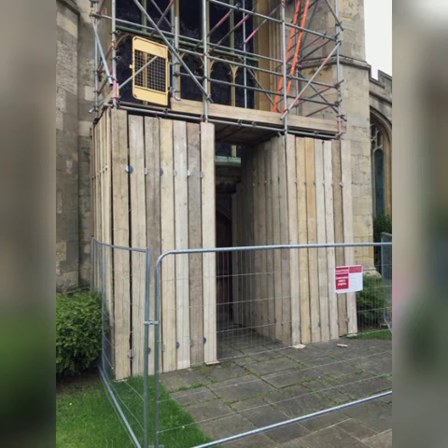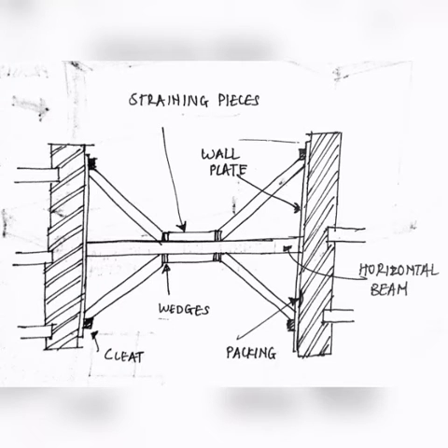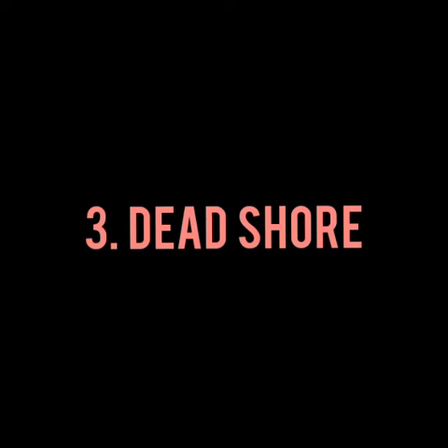This system is used where the ground does not come into use because the shores are above the ground. Flying shore consists of wall plates, needles, cleats, horizontal struts which are commonly known as horizontal shore, or inclined frames arranged in different forms which can vary when the distance between the two walls is considerable. A horizontal shore cannot be safe and a trussed framework of members is necessary to perform the function of the flying shore.